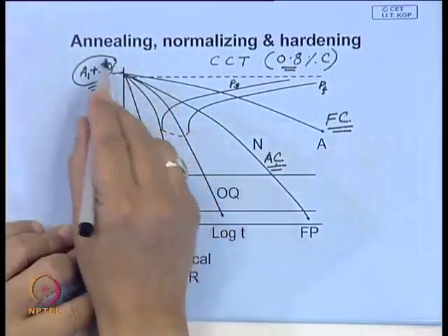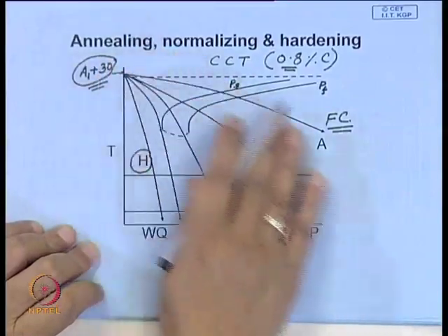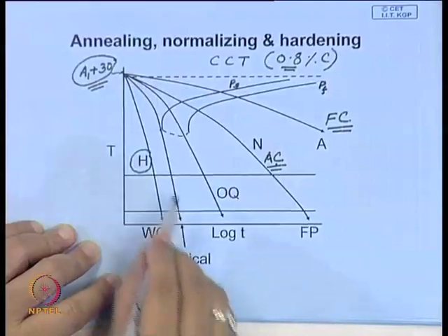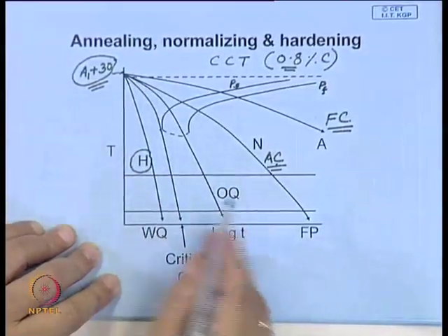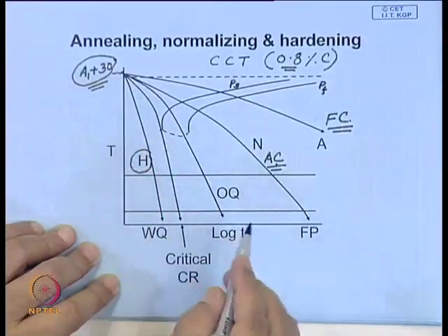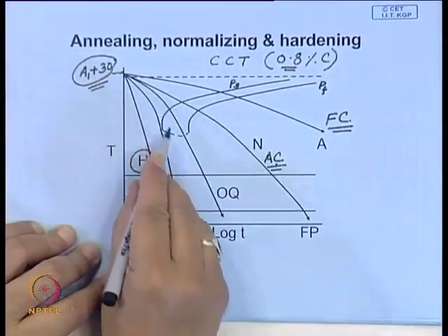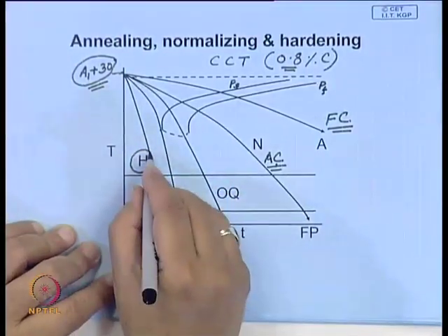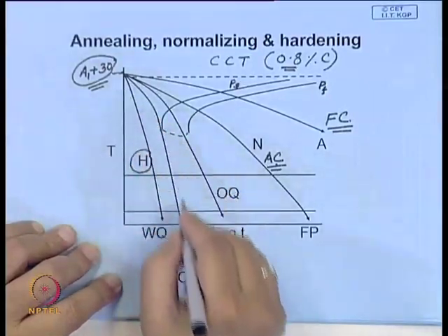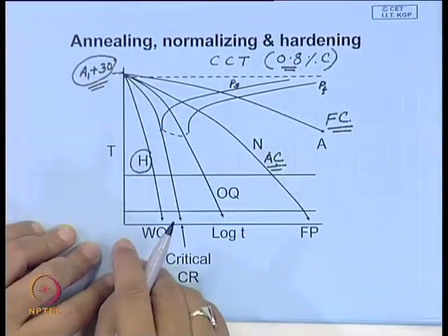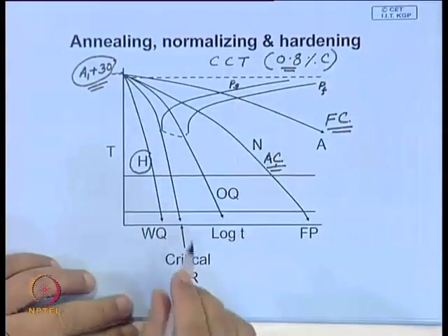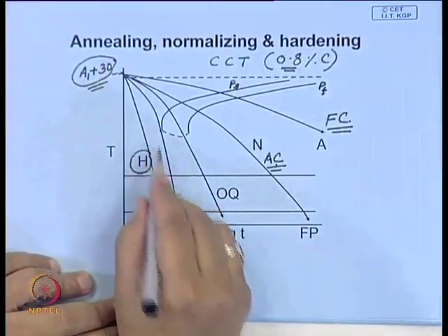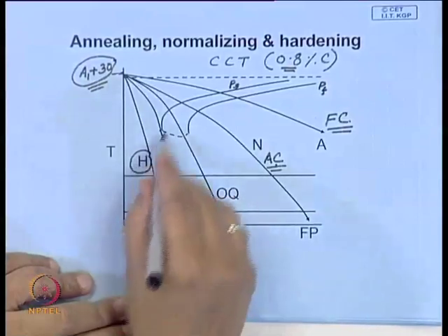And we have mentioned time and again, by continuous cooling diagram in plain carbon steel, we do not get bainite. Now, if you adopt another method of quenching, say you oil quench, maybe this is the cooling curve somewhere here. And mind you, we will come later to what determines the rate at which you will be able to cool a job. But nevertheless, what is important, to get a hardened structure, your cooling rate must be greater than the critical cooling rate.